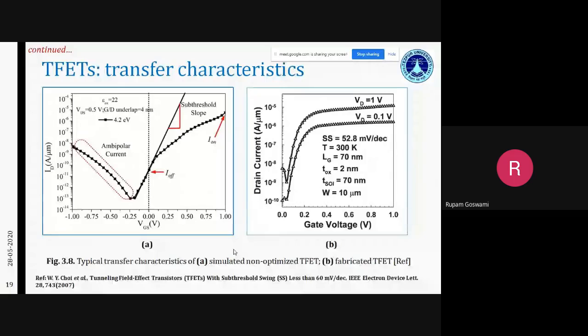Okay, so this is one of the concerns, and the reason again is the same: it operates by tunneling and the entire geometry is reverse biased. So the PIN is reverse biased because you are putting a positive potential to the drain, while keeping the source at ground or at the lower potential. That is the reason for the lower currents, and people have therefore gone to greater extents in modifying the architecture and the materials of constitution of these devices so as to improve the on current.